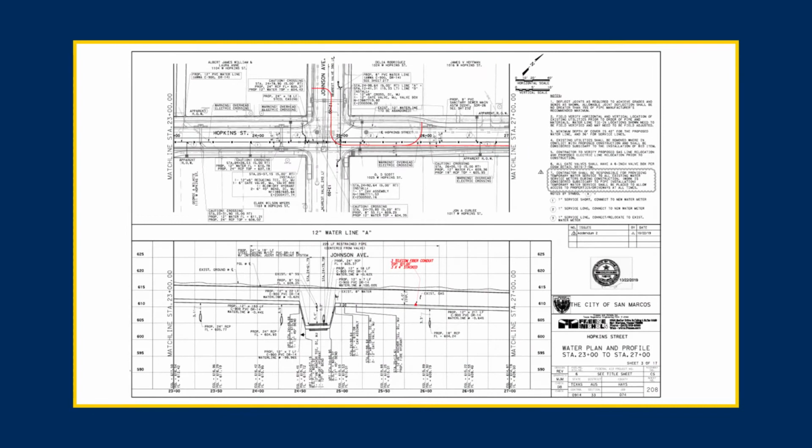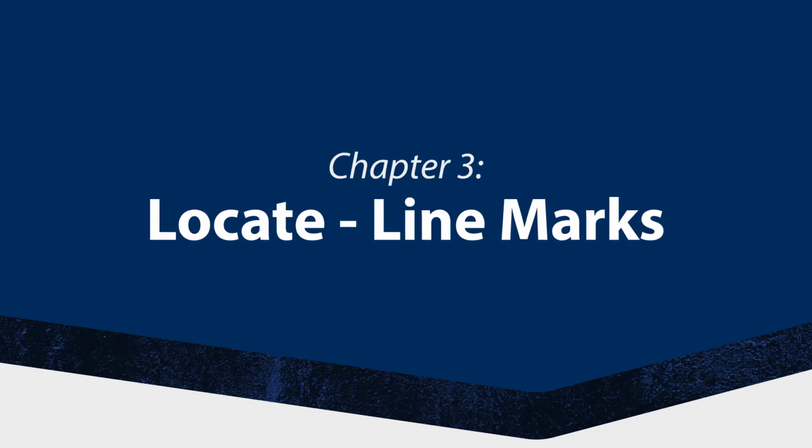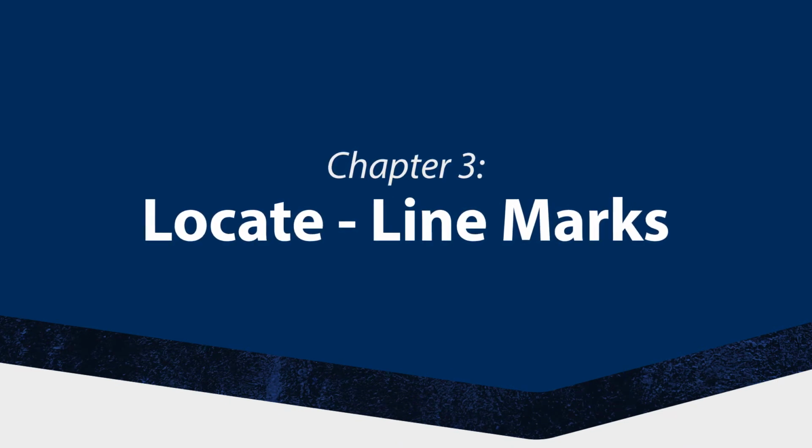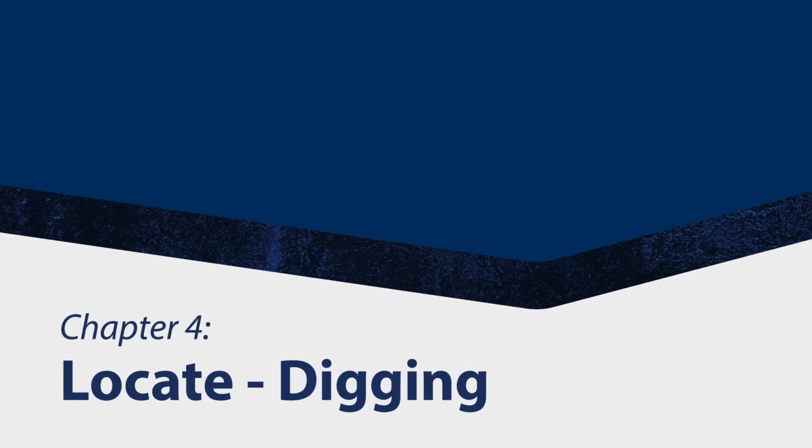Next, photograph all markings before excavation work begins and clearly document the markings on all drawings, especially if excavation activities could destroy those markings. The goal is to maintain the markings throughout the excavation. In other words, respect the marks. In the next chapter, we'll talk through how to dig around the utility lines in preparation to support them.